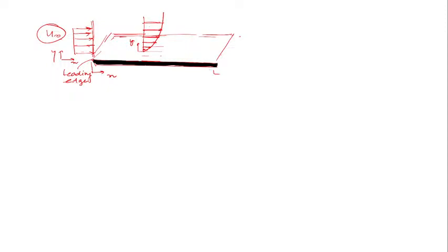You can see here the velocity increases, and I told you why the velocity close to the surface is reduced: when the fluid particles come into contact with the surface, their velocity is reduced significantly with respect to the upstream velocity of the plate. For most situations, it is valid to assume the particle velocity is zero at the wall, the no slip condition, and these particles act to retard the motion of particles in the adjoining fluid layer, and which acts to retard the motion of the particles in the next layer, and that goes on until a distance y equal to delta.